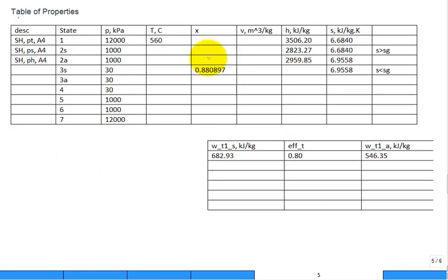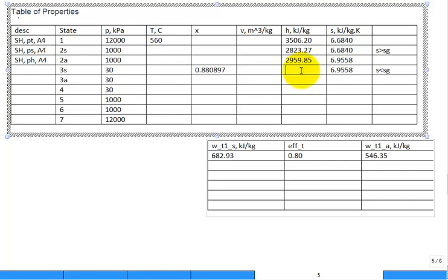So once I have the quality, I can use that to calculate the enthalpy. It's in the two-phase region, and we find the enthalpy is 2347.07. So over here in my discussion, it's two-phase. I know the pressure and the entropy, hence I get the quality and then the enthalpy. And I need to use table A3. That's our two-phase region with the pressure as the primary input to the tables.